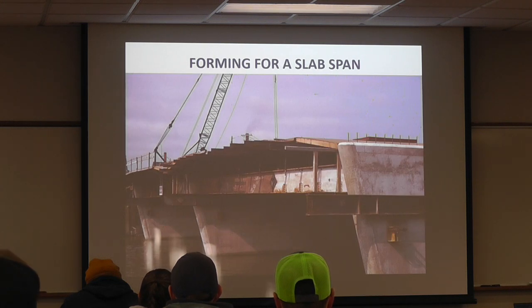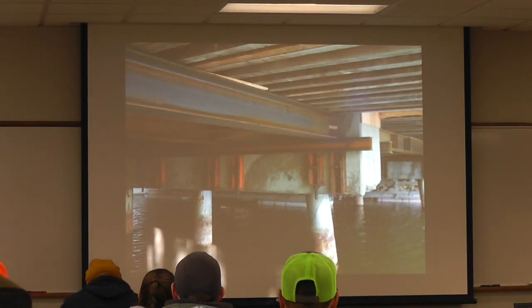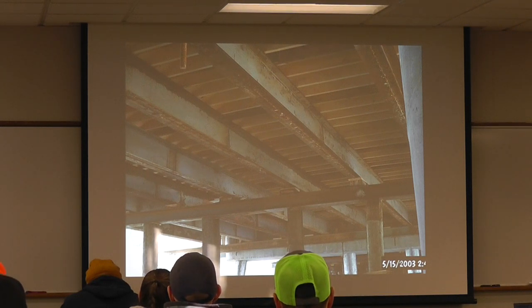More pictures of that, though you can see the through bolt configuration. So different than the friction collar we showed earlier, but just a way to connect and provide bearing. Sometimes they go down to the footing. So this is a case where you just put some vertical elements either down to the footing or perhaps this one was actually just bolted through the back wall of the abutment or the pier in this case. Again, forming underneath, some pile bent, temporary.